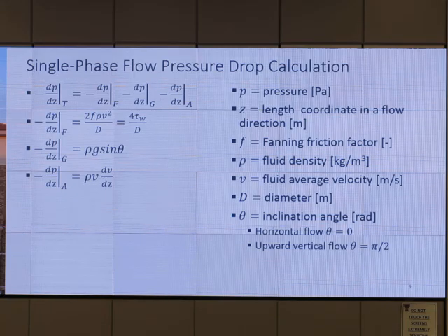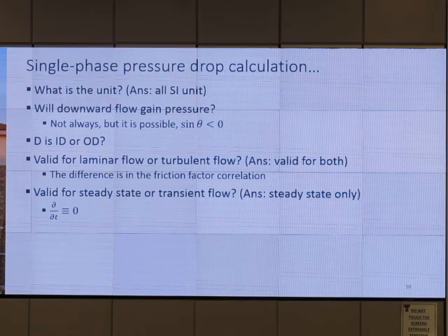If there is a change in the pipe diameter, velocity could change, right? If we have a constant volumetric flow rate and there is a change in density, it expands a little bit, so velocity can change. If there's a phase change, the velocity can change. Whenever you find a flow-related equation, ask yourself: is this for laminar or turbulent? Is this for steady state or transient? Is it fully developed or developing flow? Should it be far away from the inlet, or does it not matter?